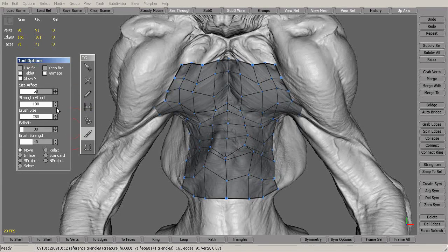Now you can change the different values here. Our brush size is pretty straightforward. I can increase the brush size with this numerical input. We can also change the brush size by using our right mouse button, and you can see that automatically changes that value. I'm just holding down the right mouse button and dragging. There's also the area of fall off, which we can change numerically here, and you can see that outer rim growing. So the area from 100% and then the fall off to no effect at all, going out to the outer portion. To change that interactively, you can hold down Shift and use your right mouse button. So again, right mouse button, and then Shift right mouse button to interactively change those values.